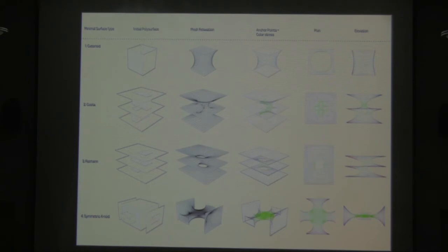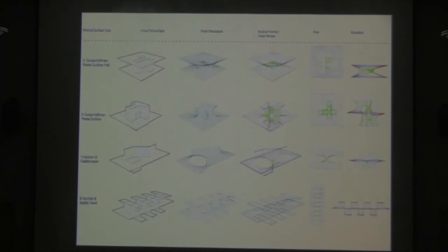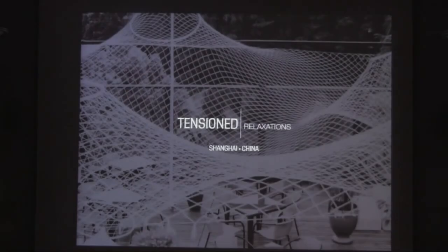And so we're interested in how we can think about those things and use the computation for what we're interested in. For us, it's more intuitive to think about how we could take these polygonal surfaces and manipulate them intuitively and reverse engineer these known minimal surface conditions into polygons, relax them through Kangaroo or Grasshopper, which is basically looking at a mesh network and minimizing the spring network into these fluid forms.